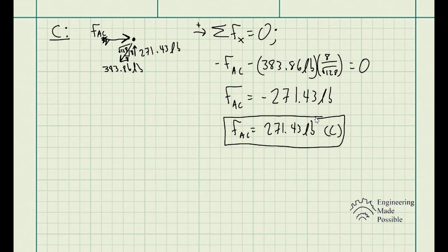And so this is the method of joints where you go ahead, you do your free body diagram, but you go at the joints. You look at the forces of those members being produced or reacting against the external forces being applied to that structure. And so right now I'd like to take some time to explain a little bit about the members in tension and compression. So let's go ahead and just assume any joint. It doesn't have to be related to this specific problem or whatever.